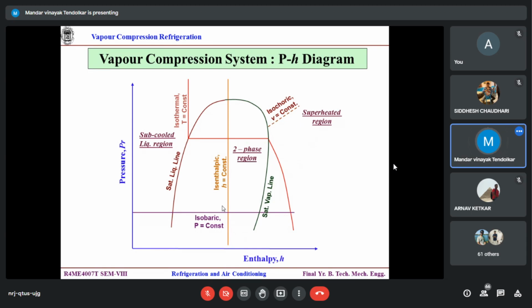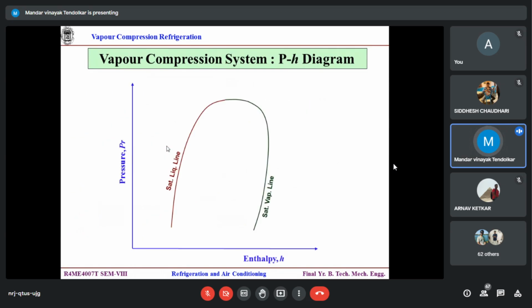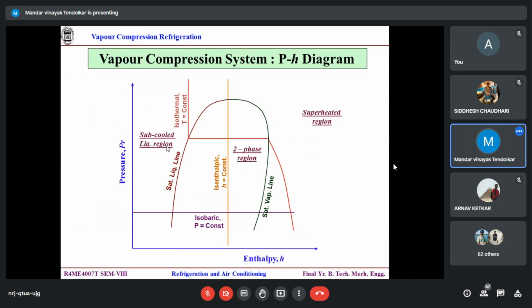Do you agree? So there will be two horizontal lines, one inclined line, isentropic compression, and one vertical line. That is isentropic expansion. There is no such case as going up and coming down again, no tilted part. On the TS chart, temperature increases over here, so we have to put it as a tilted one. But pressure doesn't change. This is a constant pressure line, correct? Here, here, here. So temperature may change, but pressure would not change.